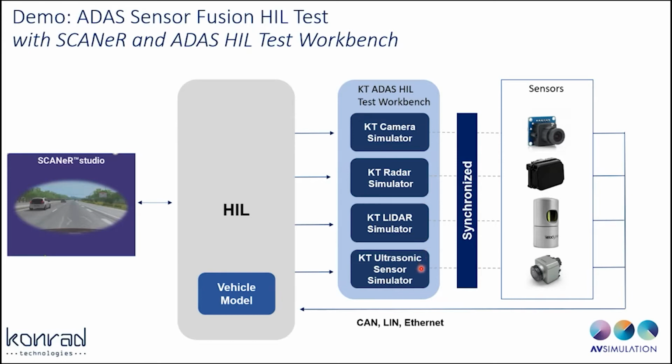And so this object data for each of the sensors is sent to the simulator system, and the simulator system in real time is stimulating the sensors according to the drive scenario. And in this way, the output of the sensors can then be collected and sent back to the drive scenario to complete the closed loop operation if needed.